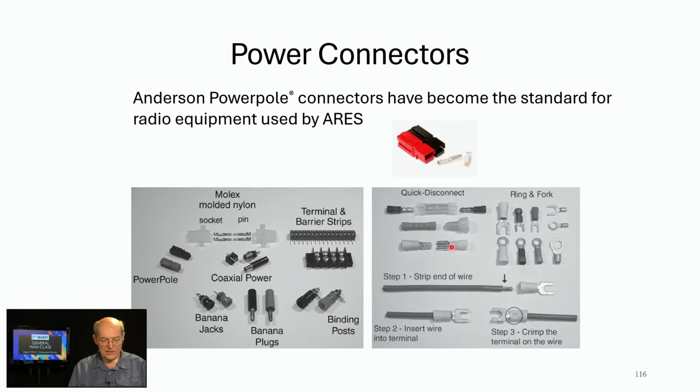Power connectors, I think you can see it. We saw one of these on the back of my ICOM. Just all different flavors that you'll have here. Anderson power poles. You'll eventually probably want to be able to put these on your radio because they're so standard. You have to be careful when you mate them up, though, to have the polarity correct.